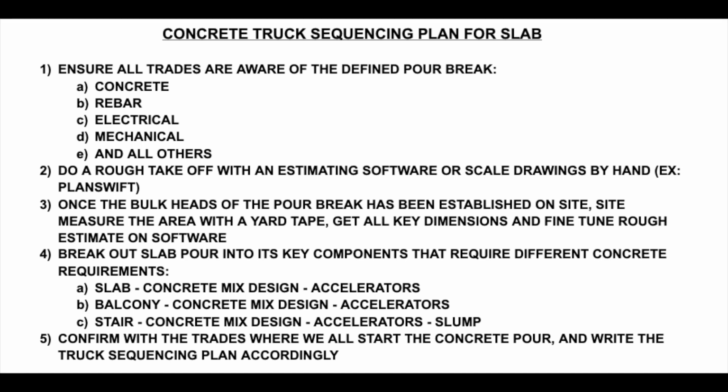Number 1, you're going to want to ensure that all of your trades are aware of the defined pour break. The pour break will be defined in conjunction with the structural engineer and the formwork concrete trade. Once that's been defined, all of your trades will know where all of the individual pour breaks are and all of the key components that they must do for that specific pour break.